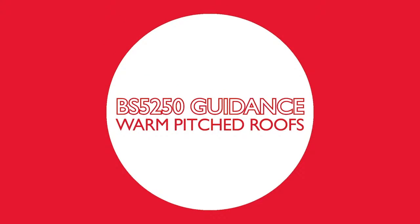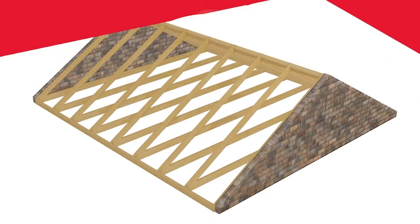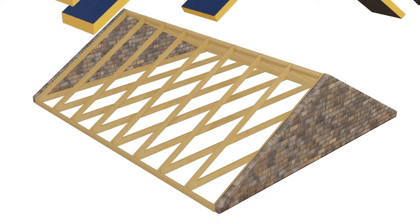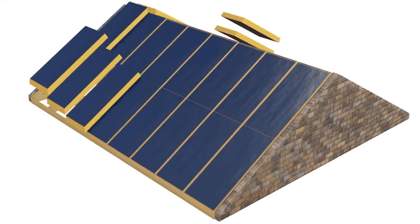In a warm roof construction, the lack of a large cold void in which moisture can collect makes the moisture control a little simpler, but care must still be taken to ensure the correct specifications are followed. Warm roof constructions are those where the insulation follows the line of the roof from eaves to ridge. The spaces within the roofing structure itself are within the heated envelope of the building.